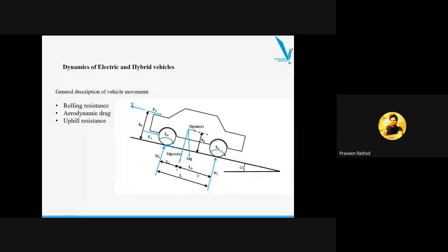the propulsion unit, whatever the propulsion unit is, will help the vehicle to overcome all the resisting forces, such as gravity, air, and tire resistance, as well as the acceleration of the vehicle, which depends on different parameters such as the different road conditions. Whenever we consider the tire of the vehicle, road condition is important. Aerodynamics of the vehicle is very important. How you are going to design your vehicle so that it reduces the drag, which we call air resistance.